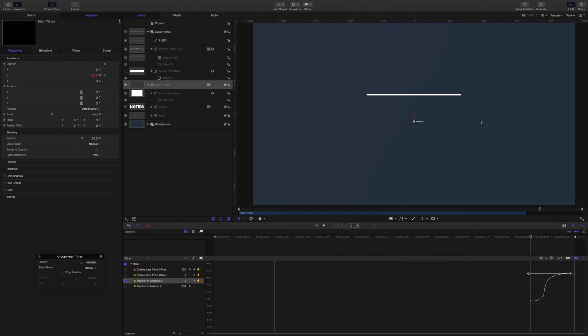And so we want now to adjust the curves of the last point and first point offset to pretty much do the same thing. So let's turn off the Z rotation, turn the last point offset, first point offset on. I'm going to drag to select them all, right click, select interpolation, Bezier, break the handles one by one. If anyone knows a faster way to just break all the tangents on all the handles faster than selecting them one by one, please shout out, let me know. I'd love to know about that. Right, so now we can work with these curves.